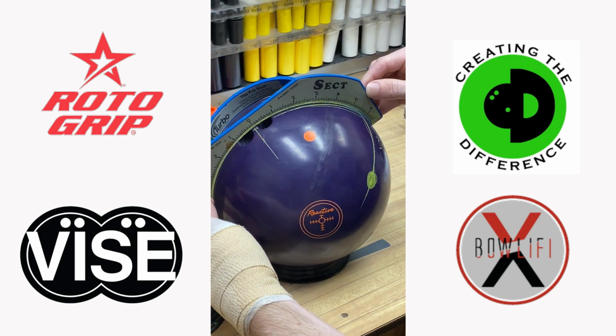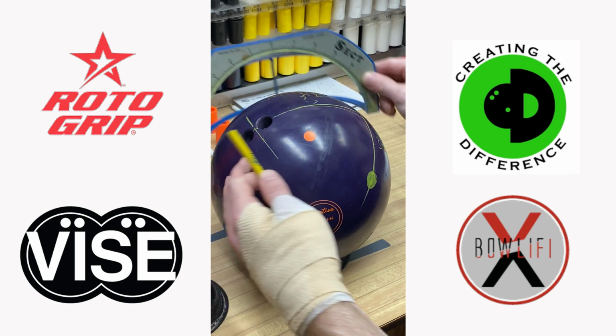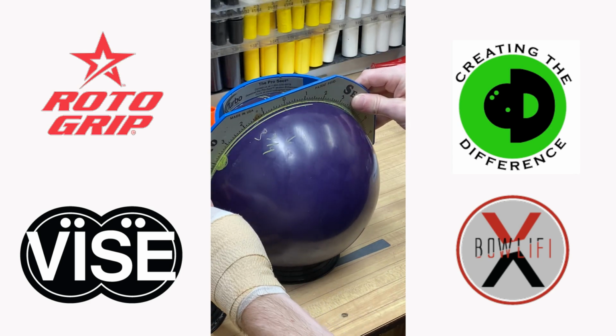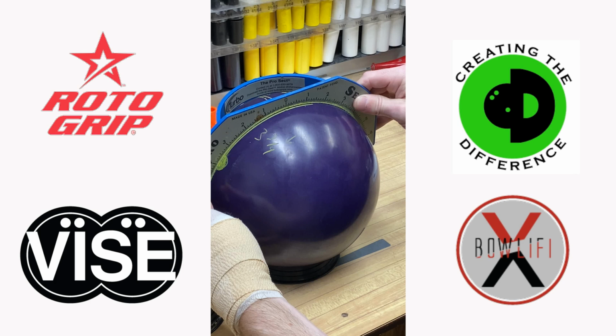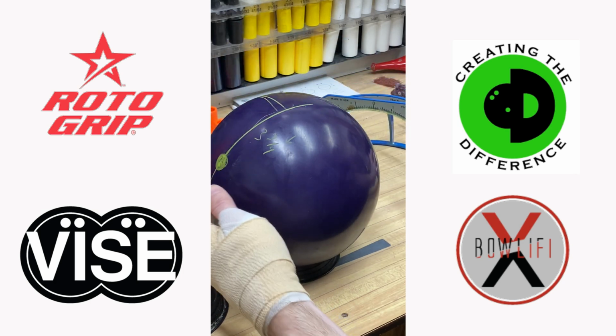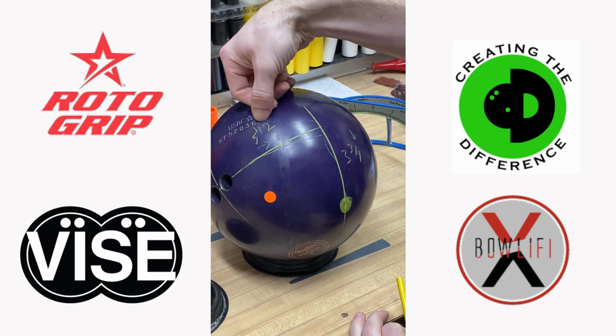So you can see here I've got the mark for the PAP along that line. And then we also draw a vertical line from that horizontal through the positive axis point. We then measure over to that vertical line and measure down or up to the positive axis point. That is going to give us the two dimensions, horizontally and vertical, of the positive axis point. In Jeff's case, 5.5 by 3 3/4.